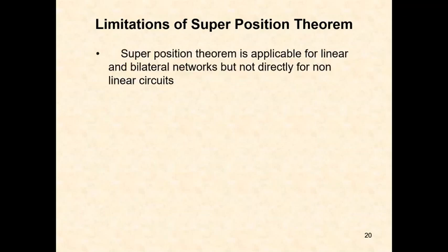And it is useful in the analysis of amplifiers and communication systems. Now, what are the limitations of the superposition theorem? So, till now we discussed the advantages of the superposition theorem. Now, I am going to discuss the limitations. The superposition theorem is applicable for linear and bilateral networks, but not directly for nonlinear networks.